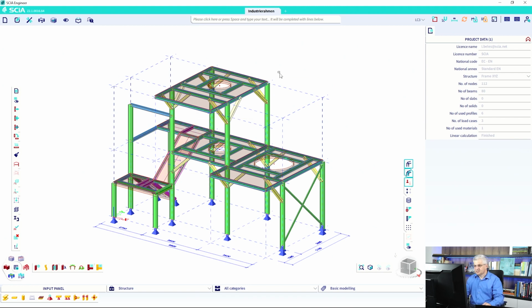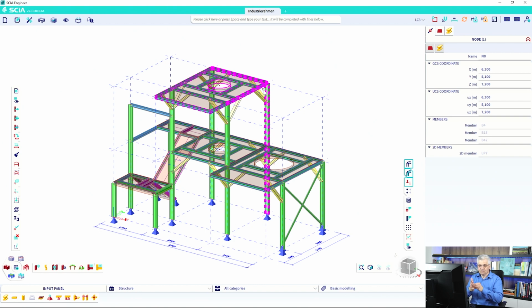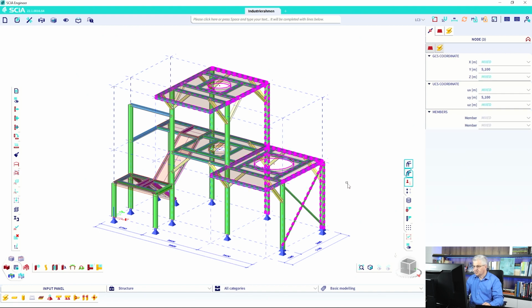You select the nodes from right to left. We have to select the node and also the members. Only selecting the node is not enough. I will also select some other members. I will select this connection too because we will need it in the future, and I also select this part, because I will need it later in my explanation. So they are selected. I go to Checkbot.